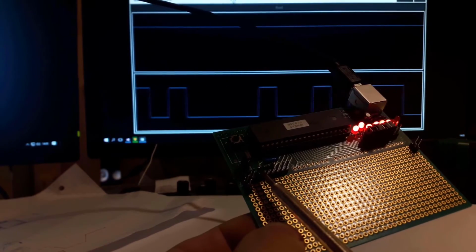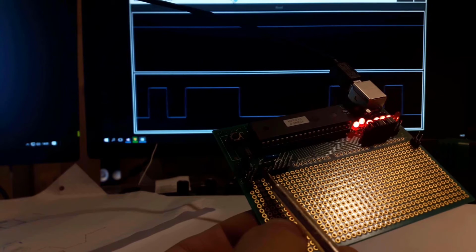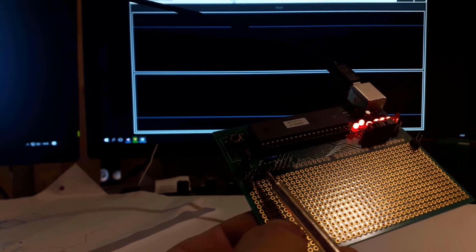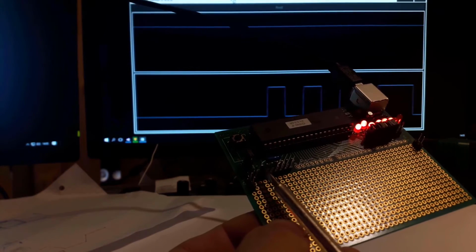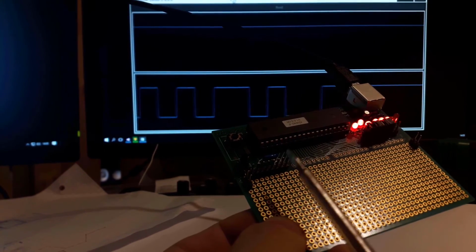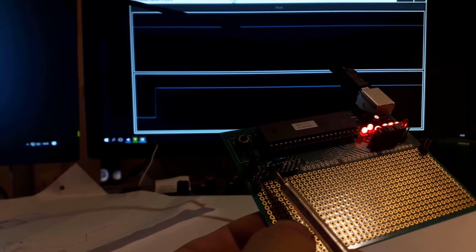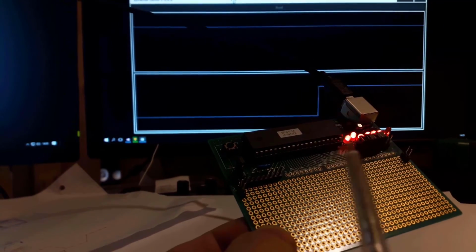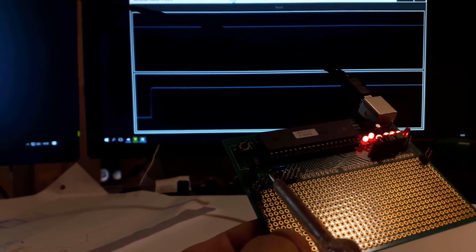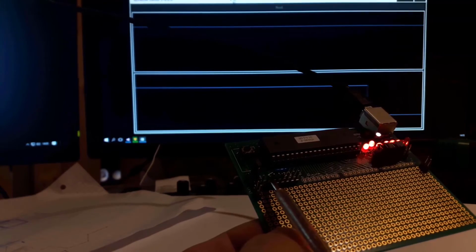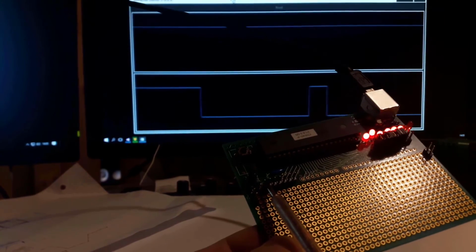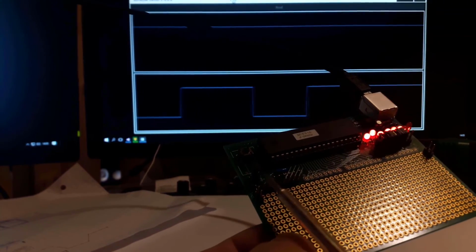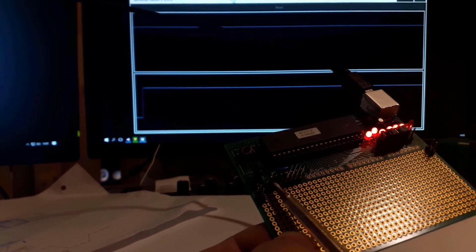So the UI that I'm going to use for this test is almost identical to the previous one, except that it doesn't just cycle once through a sequence when I press the button. It's going to switch to reading mode and stay there until I close the program. The clock and data lines are connected to pins 0 and 1 on the board, and all the other pins are pulled low. So when I make a connection with a screwdriver between pin 1, which is the data line, and one of the other pins, it's going to pull the voltage low.